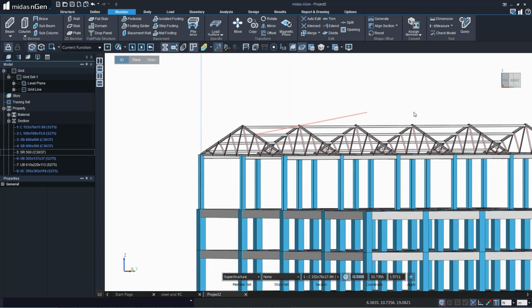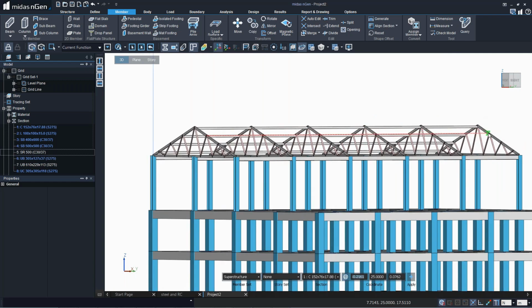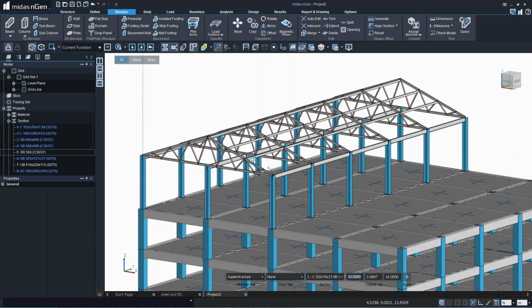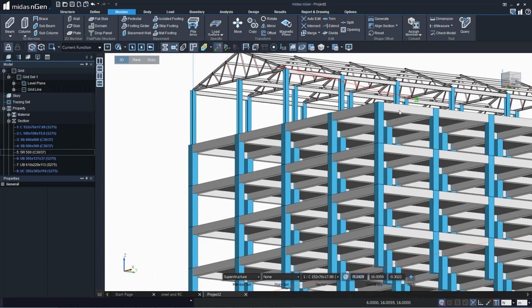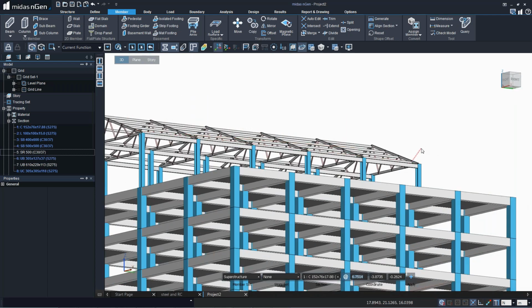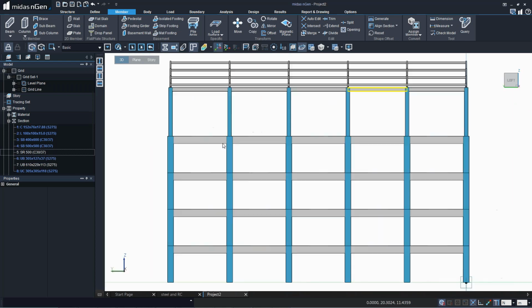Okay, so just click on the first and last point, right click to come out of the command, space bar to get back into the same command. And whenever we are snapping, we have to take care that there is a cross mark so that the nodal connectivity is maintained. So it's like a snapping tool that we have, just like in CAD softwares, we have snapping tools. So similarly, we have snapping tools.